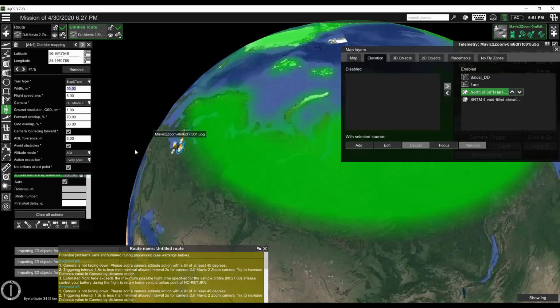It knows that at its takeoff point, ground elevation is 0, and the drone is not aware of the ground elevation at any other point. So if you perform takeoff at one location, but the actual waypoint is at a different ground elevation, there is a very complicated calculation for the drone reaching this first waypoint.